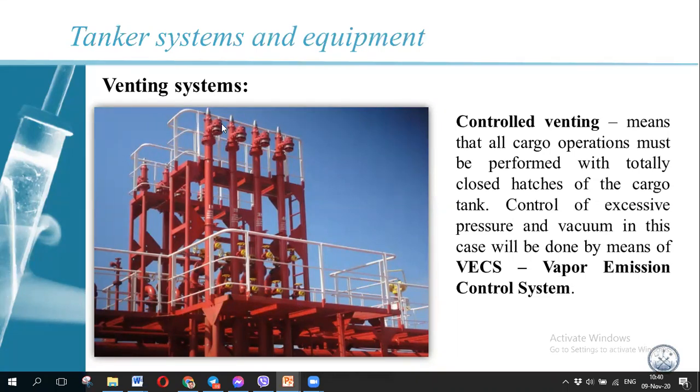But what you see, the PV valves, are a very important thing. It's your protection. If you forget to open something, the PV valve will release the gas. That is not so good. You will spoil the environment. Annex 6 of MARPOL will complain about you, but at least you will not explode the vessel.